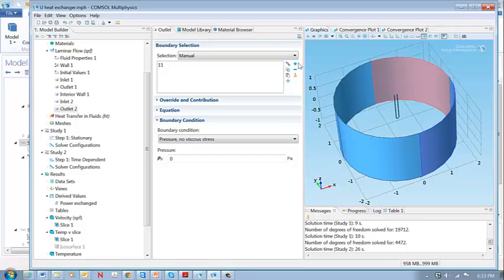And then we need an outlet boundary, and we're flowing in this direction, so that's downstream, and that's also on the downstream side. We're just going to let it be a zero pressure. The pressure would actually increase like this, but if we think of this as kind of the differential pressure, then this will work just fine as a boundary condition.